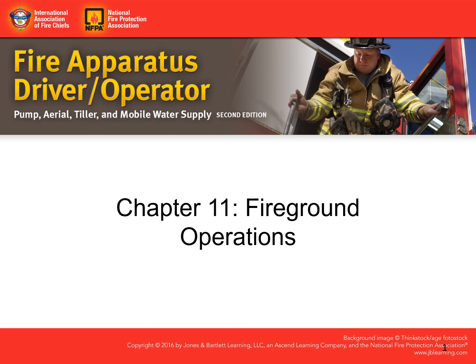This can be accomplished by using a map book with hydrant locations in it and by becoming familiar with water sources within the response area, including lakes, ponds, canals, and drafting hydrants. Another water supply evolution is furnishing water to a standpipe or sprinkler system. Fire department connections on buildings are provided so that the fire department can pump water into standpipe and/or sprinkler systems.